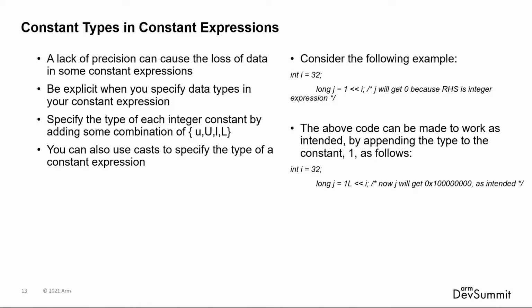This also exposes another assumption in the C language that's often missed and can be avoided if you simply are explicit when using constant expressions. C will promote all values to a signed integer when not instructed otherwise. Therefore, when you have a constant expression where a value is intended to be unsigned, like an absolute address or a bit field representation, it's always good to append a small or large u depending on the size of the field you want.